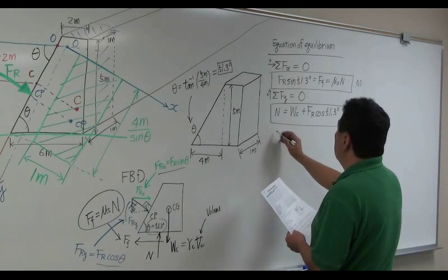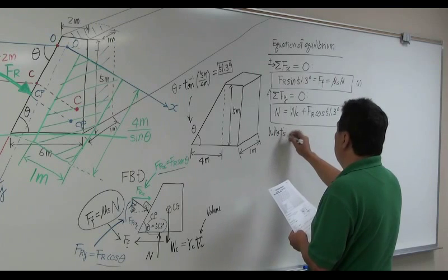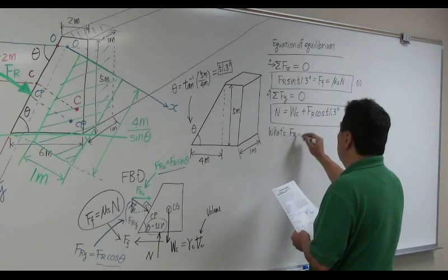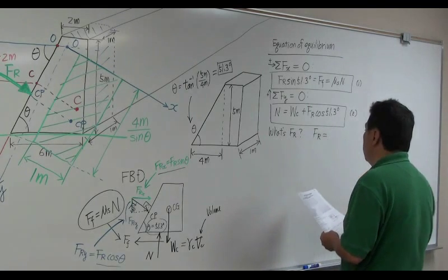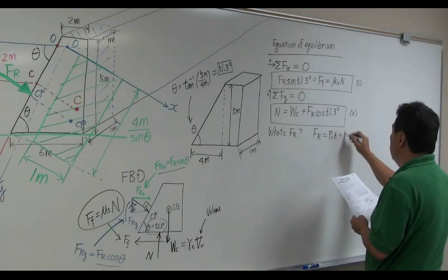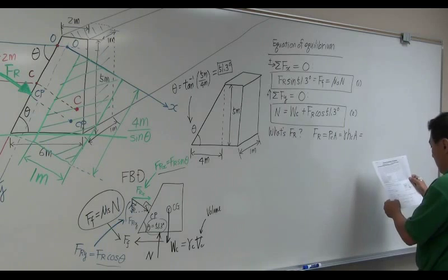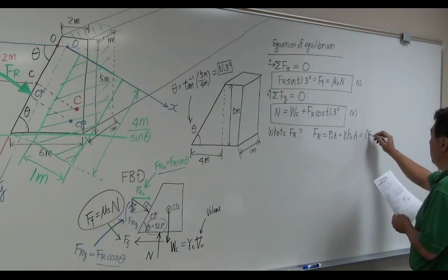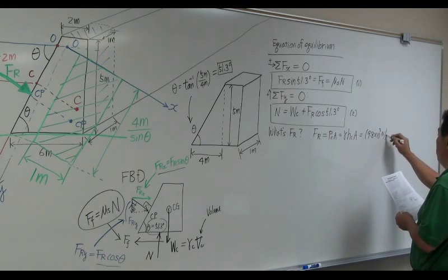So first of all, what's Fy? Magnitude of hydrostatic resultant force Fy. Of course, you know this is Pc times A. This is gamma times hc times A. Okay, so let's find out. 9.8 times 10 to the 3 Newton per meter cube.